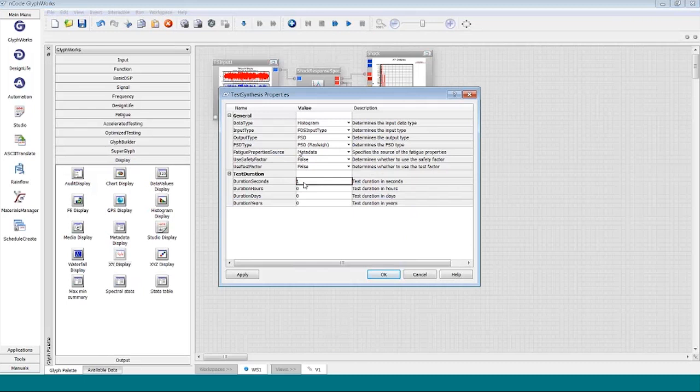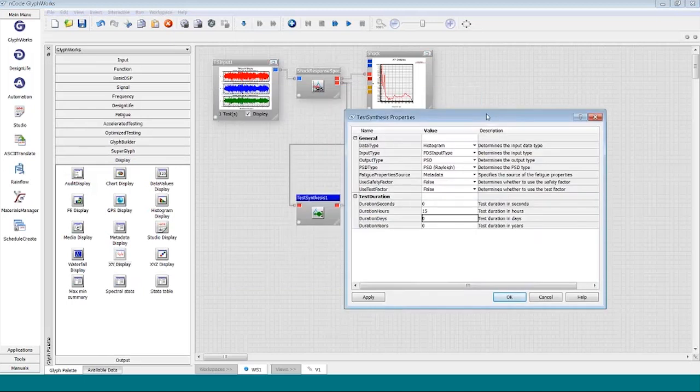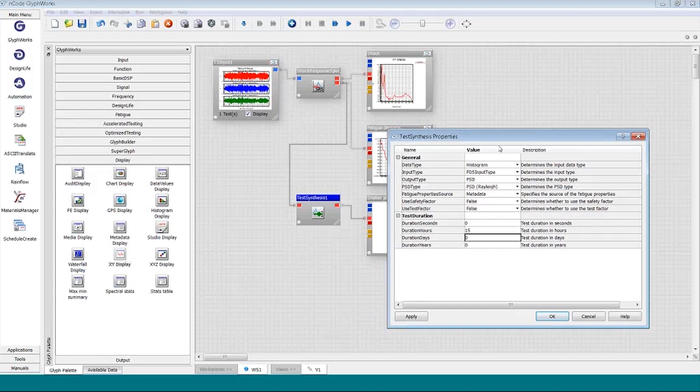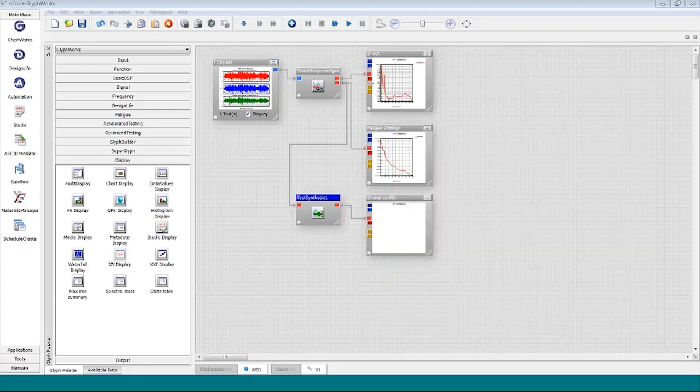For example, a really critical input here is what's the duration of my shaker profile test going to be? I'm going to try running, let's say, a 15-hour test. So the magnitudes of the shaker profile should be calculated such that in 15 hours of that GRMS profile, I produce 2,000 laps worth of fatigue damage. So let's take a look at that right now.